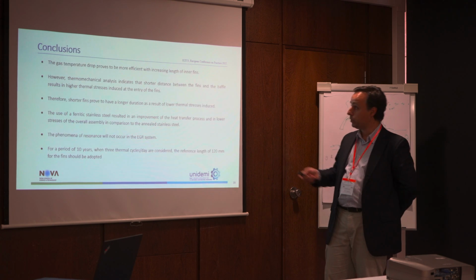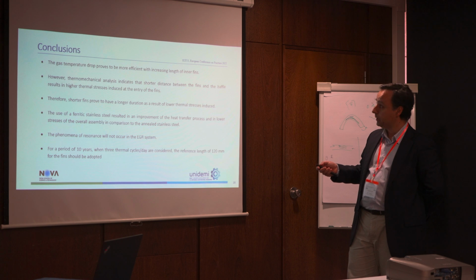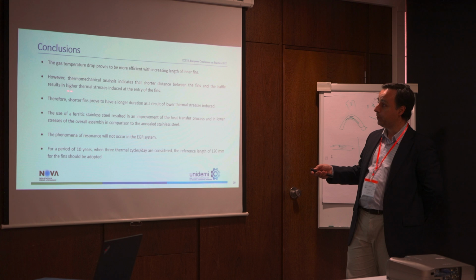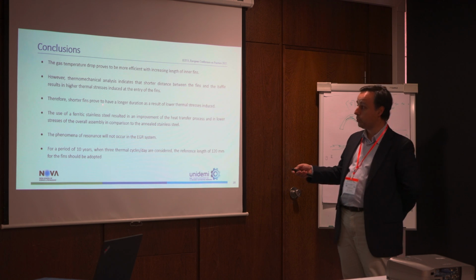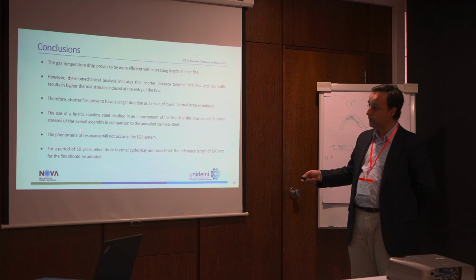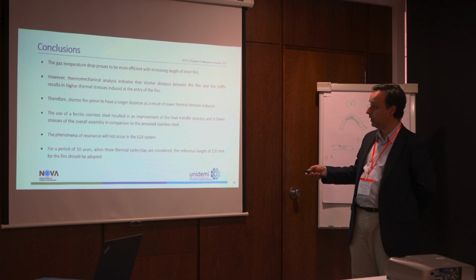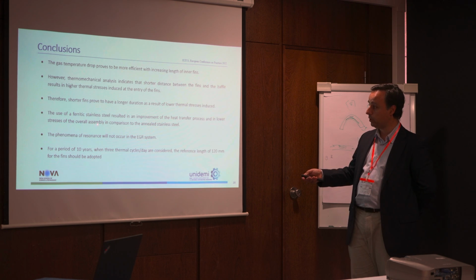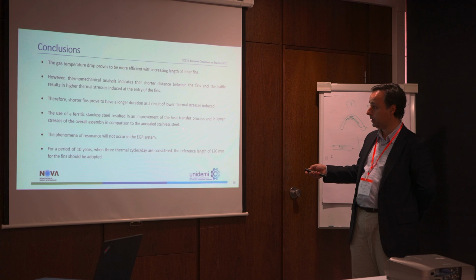Okay? So to conclude, the gas temperature drop proves to be more efficient with the increasing length of the inner fins. However, thermomechanical analysis indicates that shorter distance between the fins and the baffle results in higher thermal stresses induced at the entry of the fins. Therefore, shorter fins prove to have a longer duration as a result of lower thermal stresses induced. The use of a ferritic stainless steel resulted in an improvement of the heat transfer process and in lower stresses of the overall assembly in comparison to the annealed stainless steel.